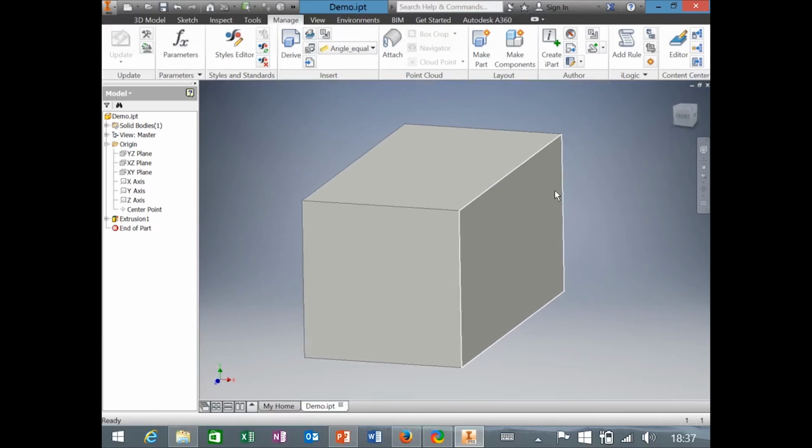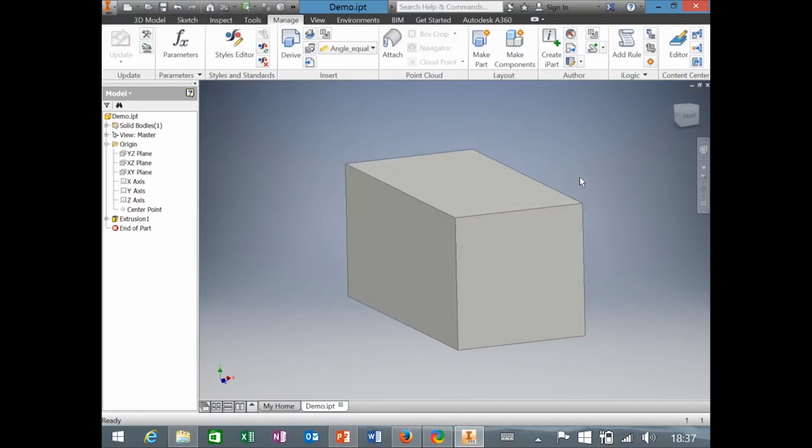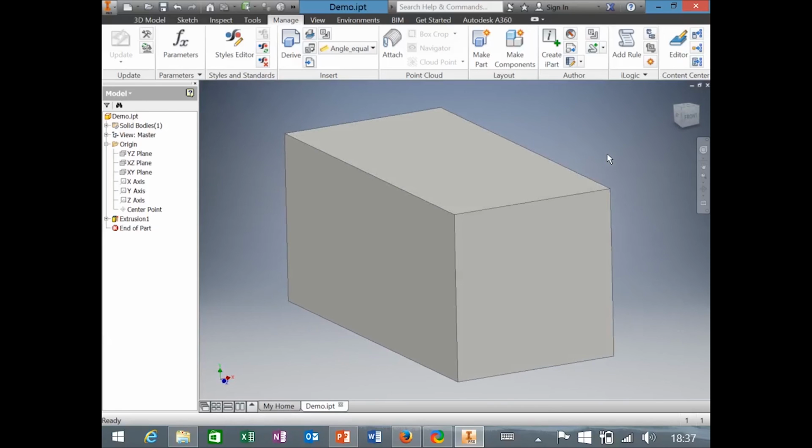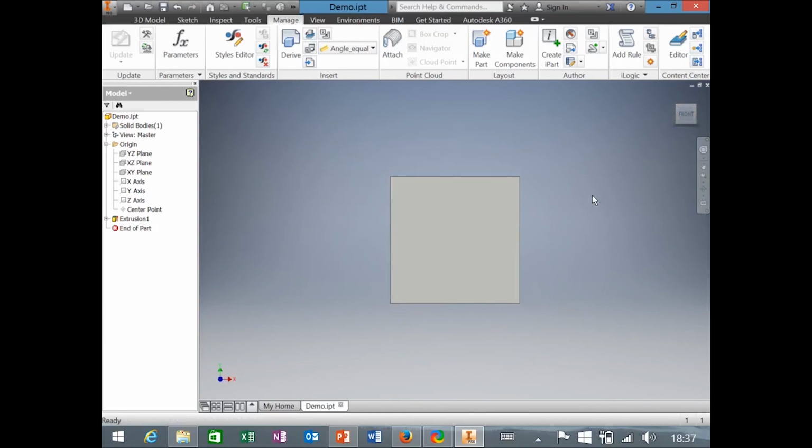You can also change the view perspective. So right now, this is projected in something called orthographic projection, which is where objects do not change size based on distance. So you'll notice that I can orient this model to face the front plane, and it looks like a square. Now, this is contrary to your daily perception, because usually if you look at an object like this head-on, the face in the back would be smaller than the face in the front, although it would be occluded. So if you had a different shape, you might be able to see that there's an effect due to perspective. Like I'm shorter at this distance than I am if I'm right next to you.